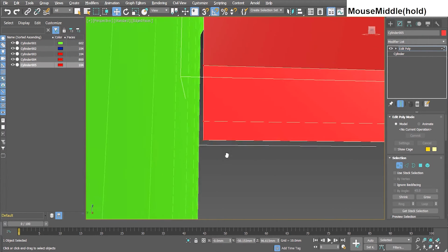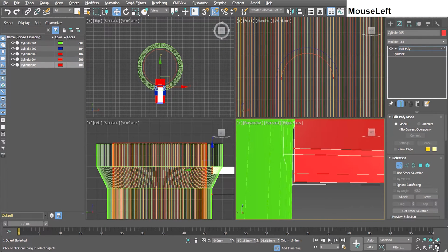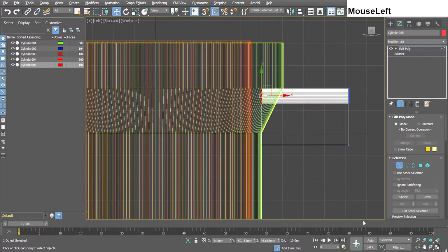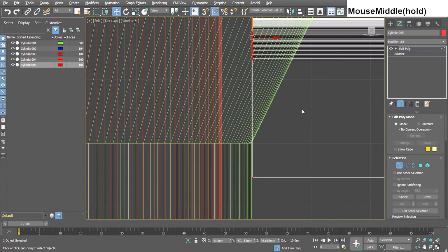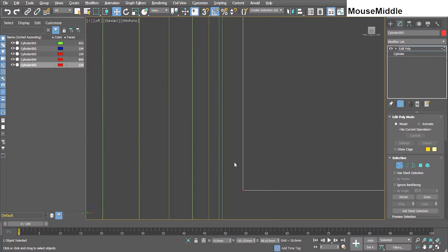What I'm trying to do is get it close to this wall without going through, which if I unmaximize the view, a view like this left would come in pretty handy. Of course, something else I could do is remember that the radius on this is 50 millimeters, and I could go in here and have that be 50.1 or 50.001 millimeters off.